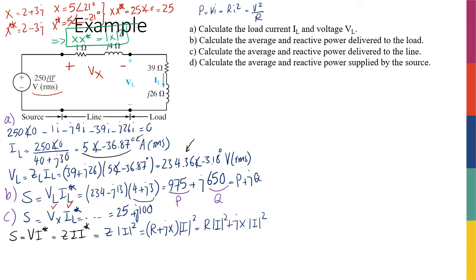One of them is real, so I can call this P, and the other one is imaginary, so I can call this Q. So really my P, the real power, is the real part of my impedance, R, times I squared, and there's no surprises there, right? If I have a resistance that is the real part and a complex current, to calculate the power it's going to be R I squared. For any resistor, at the end of the day, the real power should be R I squared. And then there's the imaginary part, which is X I squared as well.